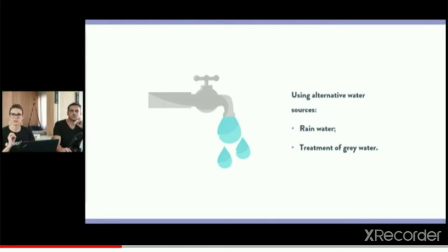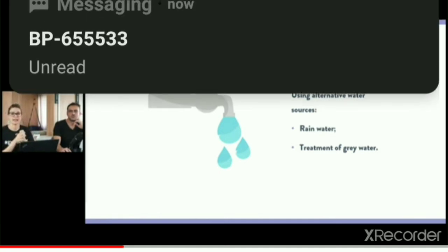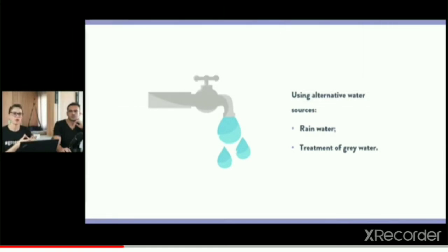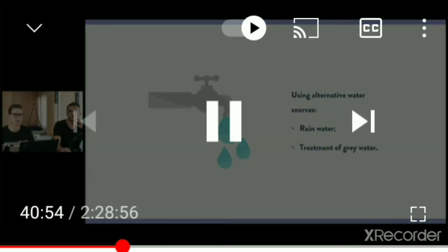Also look at your local legislation. Here in our city, we have a local legislation that we cannot use gray water for anything other than watering our gardens. And this requires a treatment. It requires that the sanitation company comes and checks for this and approves, and you have to create tests for this water so you are able to do this. Otherwise, you're going to get a fine. So understand your legislation and understand the type of strategies you're applying, the techniques, and have some sort of guarantees that you will be provided with quality.